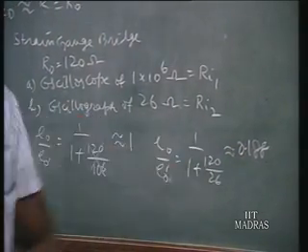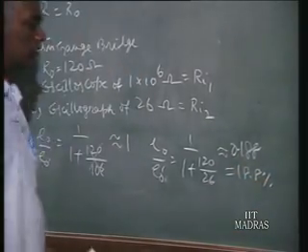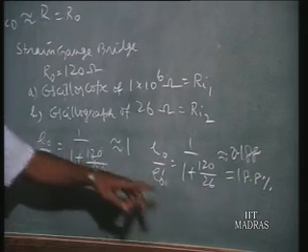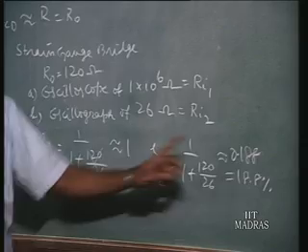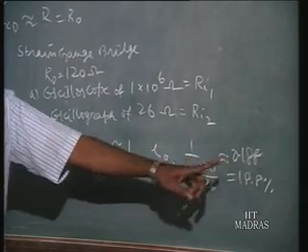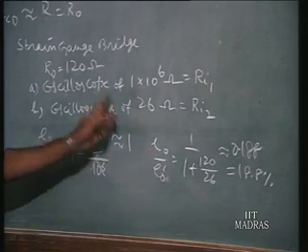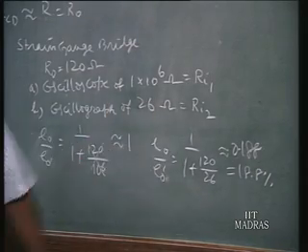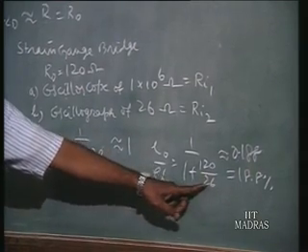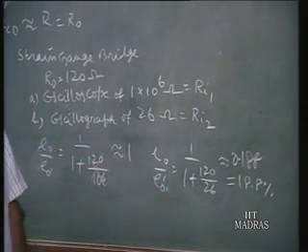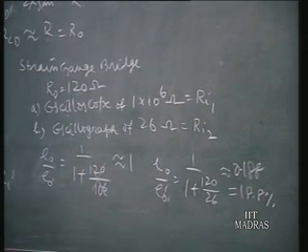That means EO in terms of percentage is 18.8%, or say if it is 20%, EO will be 20% or 1/5 of EO dash. So EO will be 1/5 of the theoretical value. Suppose EO dash is going to be 5 volt, and what we get in this instrumentation is only 1 volt. 4 volt is lost by loading effect. So there is a heavy loading effect since the input instrument has very low resistance. So we normally say such instrumentation should not be used, but here there is a special property.